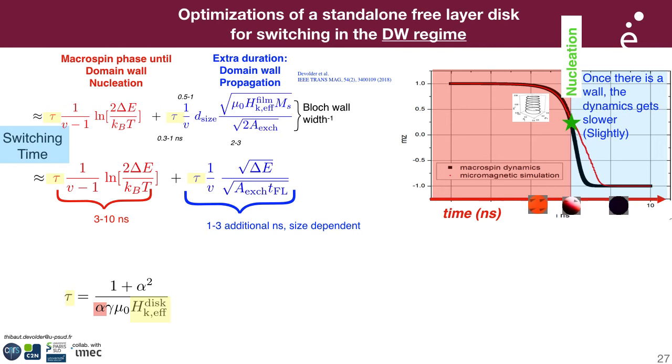And then there are many ways to calculate the switching time, so the part that is due to the motion of the domain wall through the device. Essentially, the one I prefer is this one, because it evidences that the natural timescale comes also in this part of the switching time, and the other terms are, of course, how much voltage you apply.